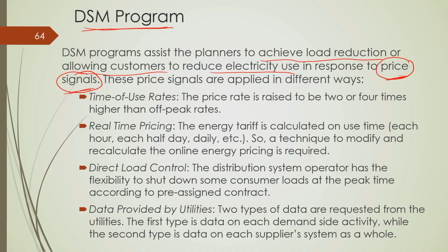Okay. And one of the aspects by which you can make your demand side management (DSM) program successful is by devising a proper energy pricing signal. Now, as I said, how the customers will use their load and what sort of appliances they will use, these are not in the hands of the electric utility, but you can devise a pricing signal so that you can motivate the customer indirectly to reduce their consumption during peak, or encourage consumption during off peak, or shift this load.